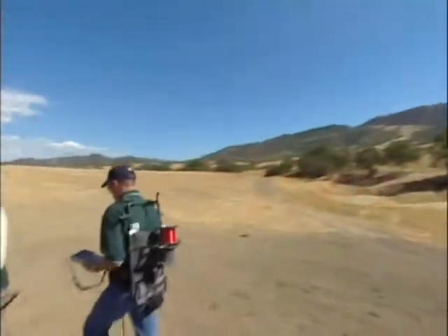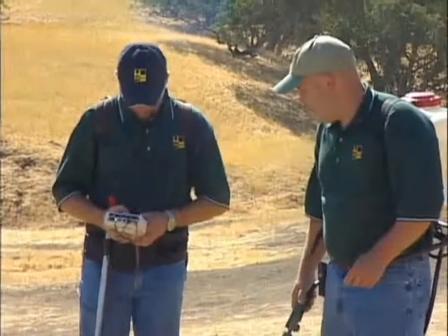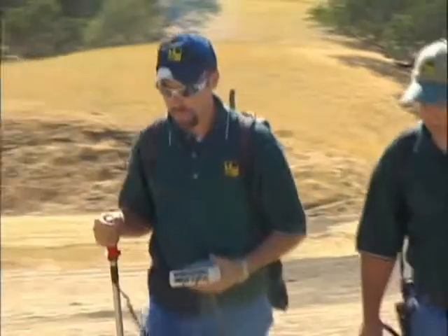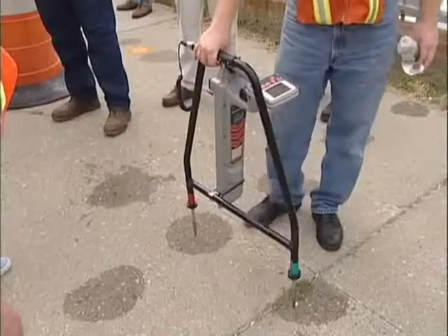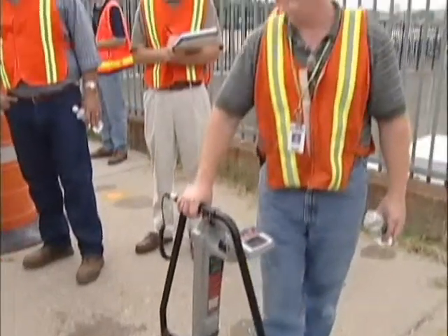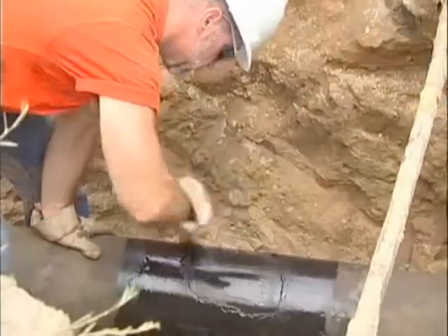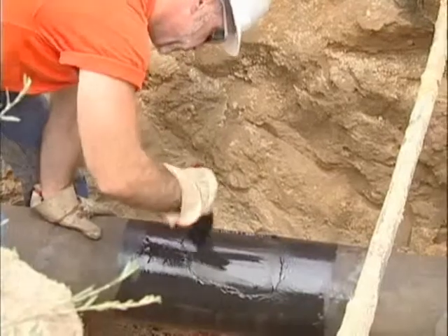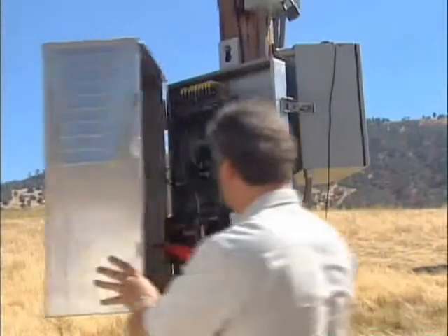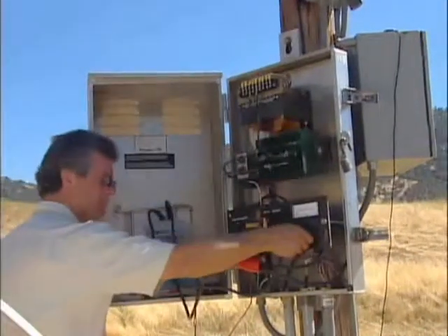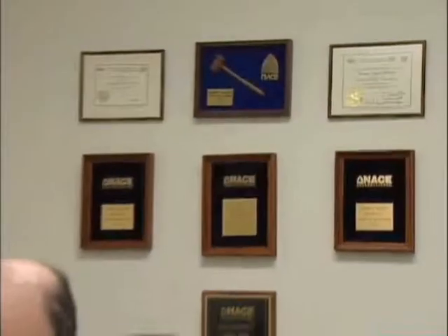In the early 80s, many pipeline operators began supplementing the minimum code-required corrosion control monitoring provisions with additional external corrosion testing, such as close interval survey. Additional corrosion testing methods, such as voltage gradient and attenuation survey techniques, were developed in the 80s and 90s. Since external corrosion protection of a buried pipeline is primarily dependent on a good coating as the first line of defense and cathodic protection as the second line of defense, most of the testing was designed to locate coating flaws and determine the adequacy of cathodic protection.